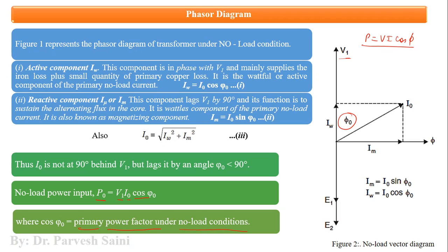So the heat effect because of the eddy currents and hysteresis, and the leakage of the flux in the primary winding, all these effects will be there, and these appear as losses in the primary winding. We generally call these losses the iron losses, right?